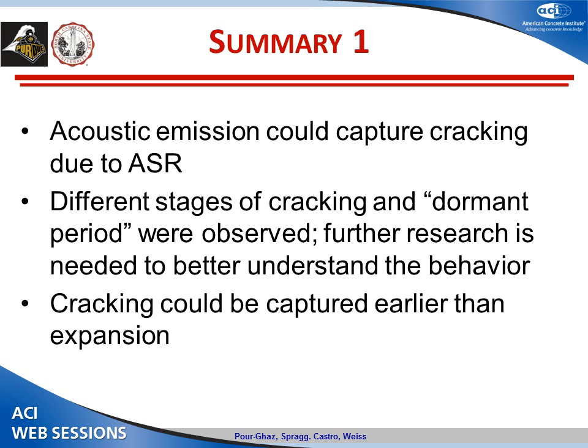Now, based on this, we performed the experiment at 38 degrees, and we used this on a larger sample. Based on the aggregate that we have, we really slowed down the system, and this was to have a much more controlled system. We need to do more investigation and research on the effect of temperature and geometry of the sample. Now we saw that acoustic emission can capture cracking due to aggregate expansion and ASR. We saw different stages, or for lack of a better term, a dormant period was observed, and more research is needed to better understand what is happening inside the system.